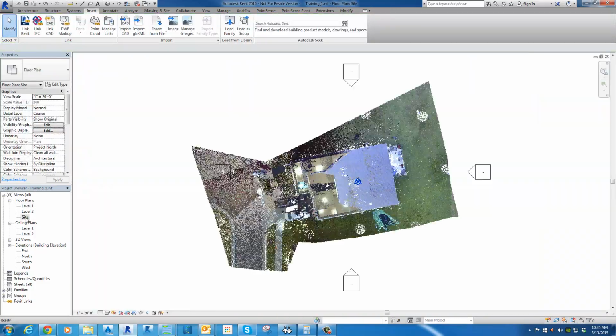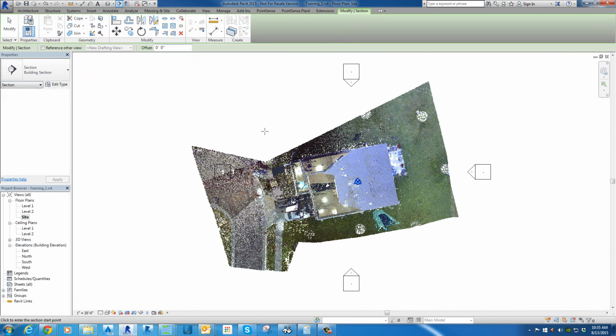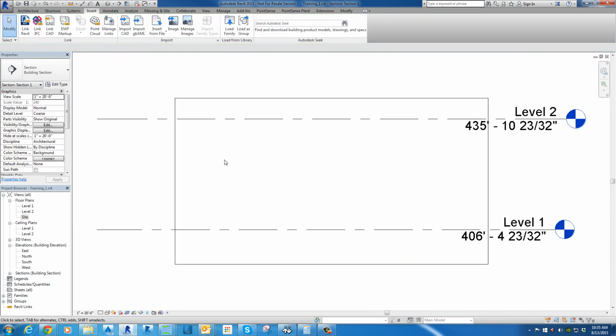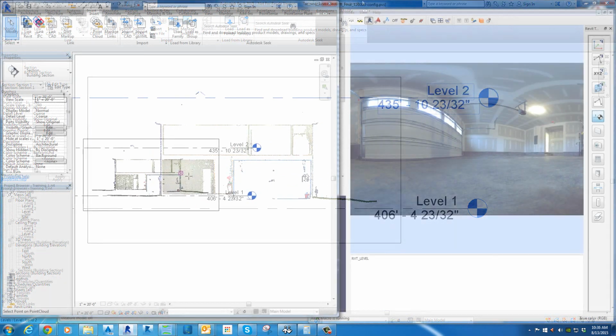For our next step, I'm just going to set up some levels for us to design, so that when we start doing our walls, our levels are set at the correct height, and our walls will then also restrict to those level heights.